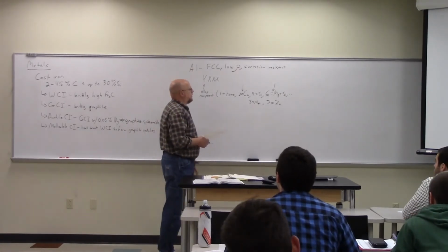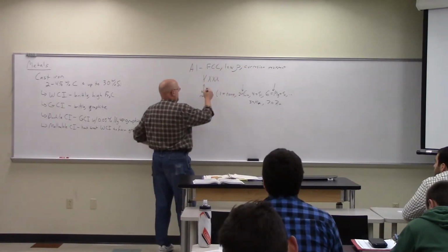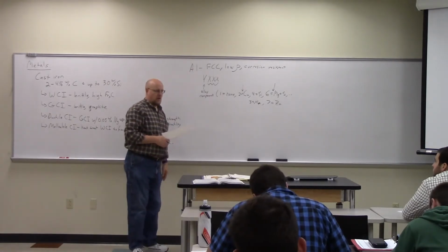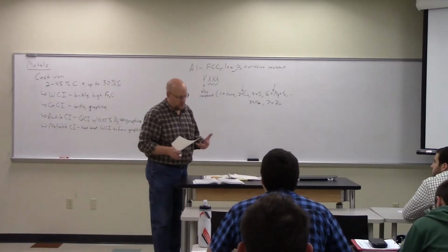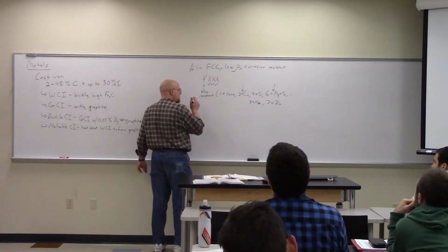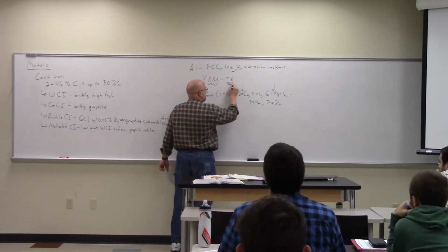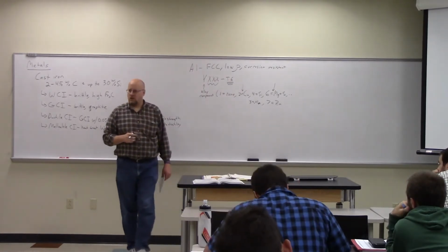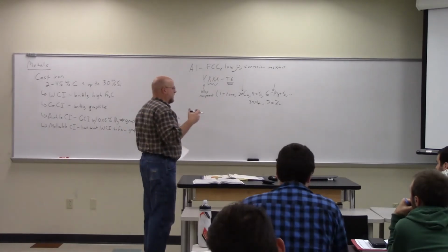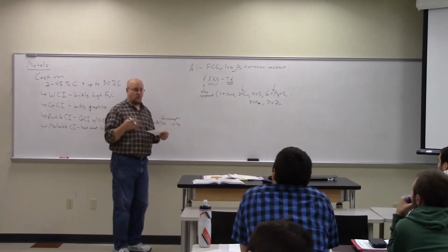They have a wide variety of properties, and this part is just sequential. It doesn't have the same kind of meaning. Again, there's no quantitative meaning for the XXX. But there are a number of tempering designations that distinguish how the thing is heat treated. And the heat treatment can substantially change the properties.